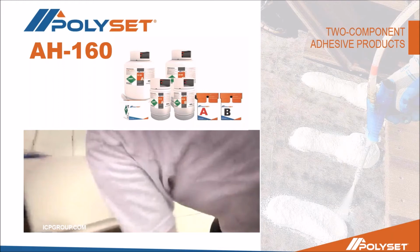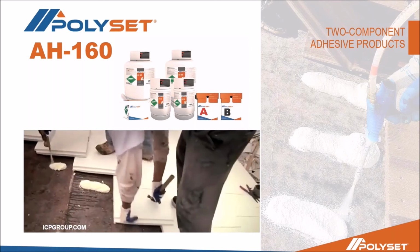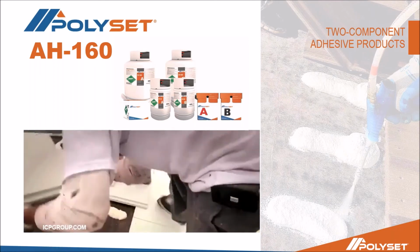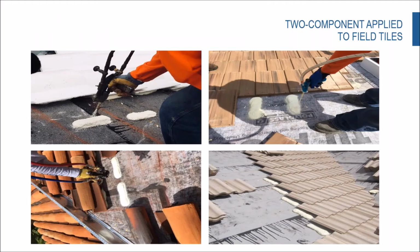But again, there are various sizes of 2-component products for the projects that you have going on. This is a quick little video of a 2-component product being applied to a deck. You can see how fast they're going. This is what's called a stair-step method, where you have one guy pulling the trigger of that metal gun, the other guy right behind installing the tile. You have a pretty good crew that's pretty knowledgeable in applying adhesive. You can get a lot of squares done pretty rapidly using the system.